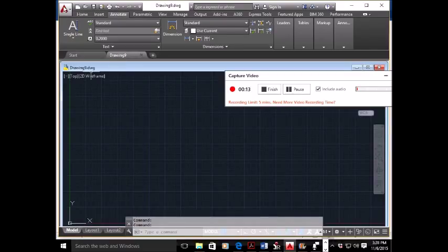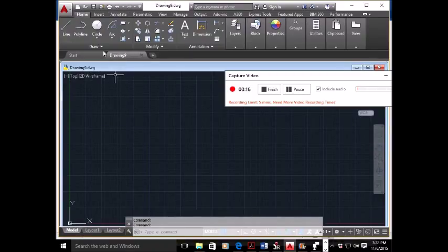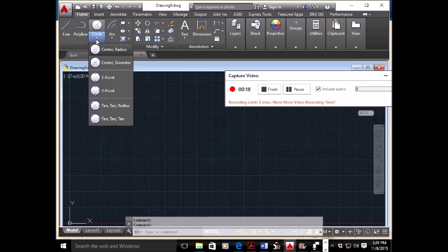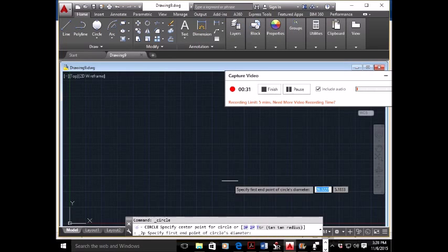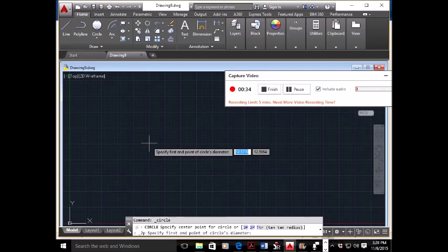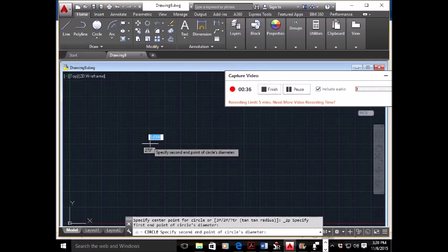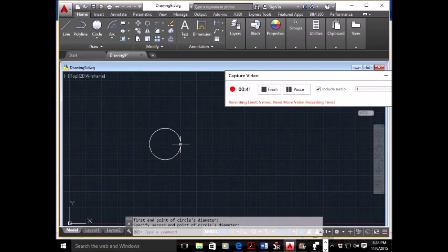You can view text that has scrolled out of sight by clicking the up pointing arrowhead at the far right of the command window. Right now, the command line displays the words "type a command" in a box, see figure. This tells you that AutoCAD is waiting for a command. When you click a point in the drawing area, you see the message "specify opposite corner." At the same time, the cursor starts to draw a window selection that disappears when you click another point. The same message appears in the dynamic input display at the cursor.